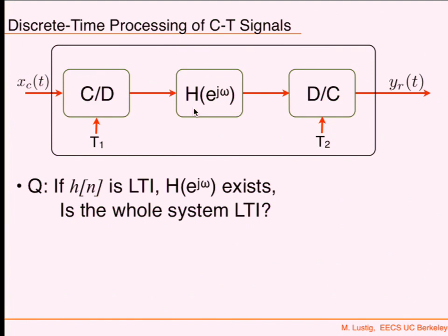I actually don't think that's the case. I mean, I can see that I sample my voice at 44 kilohertz. My voice is only 5 kilohertz wide. Then it gets to the computer, it's downsampled, does some processing at 5 kilohertz, and then from 5 kilohertz it goes up, it changes the rate, and then goes and reconstructs at continuous time. So it doesn't have to. The sampling rates have to not introduce aliasing. Oh, what if I had aliasing?